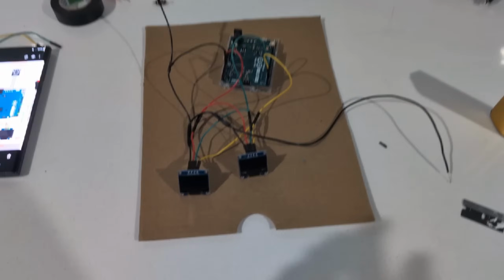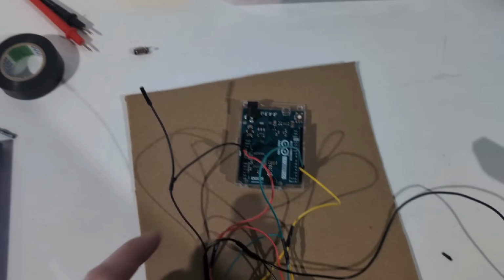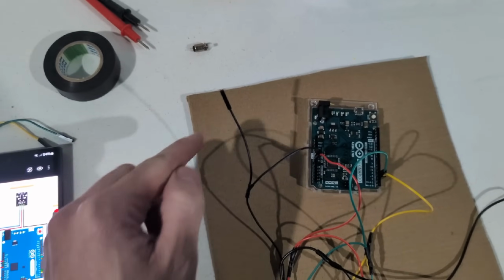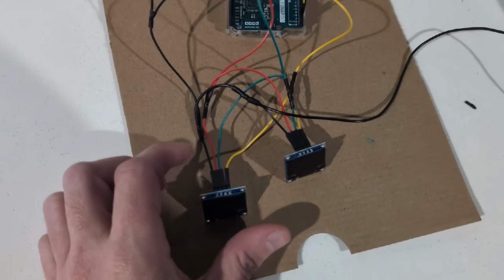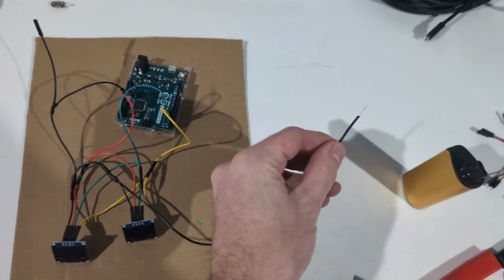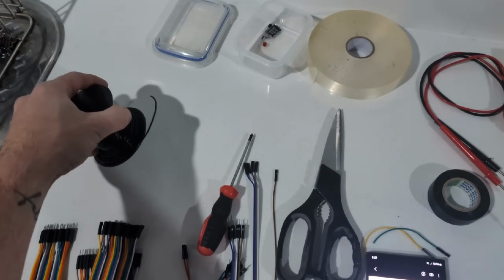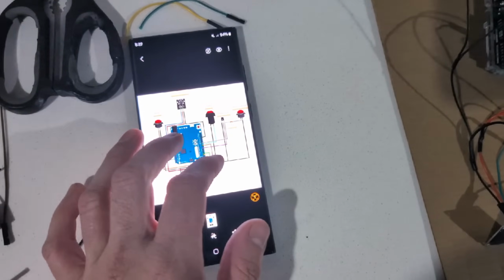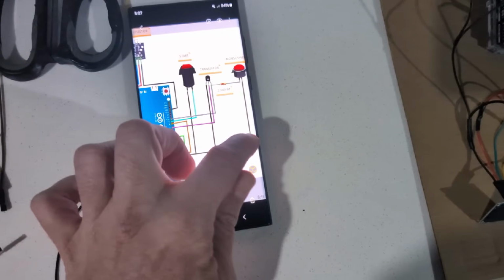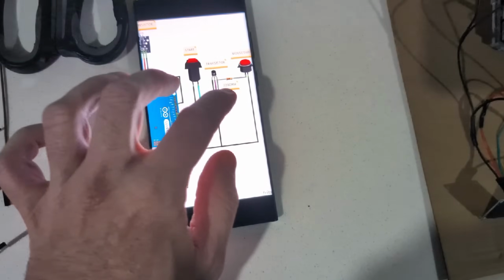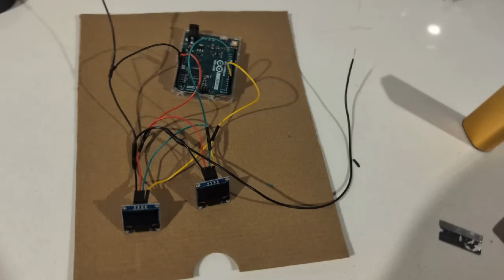All right, so that's the earth that I've done here. It's a little bit messy, but we've got earth ground from here. This is going to go to one of the switches. Earth to here, and then I've actually ended up just using some wire that I had because we're going to need to extend this out for earthing a couple of different things. Mouse switch, transistor, and the start button. So that's what it looks like there.